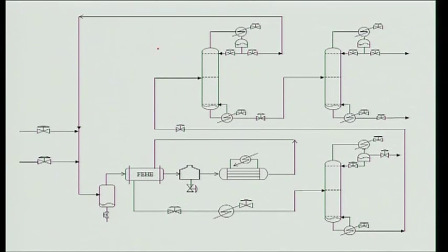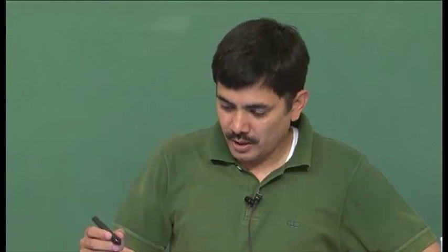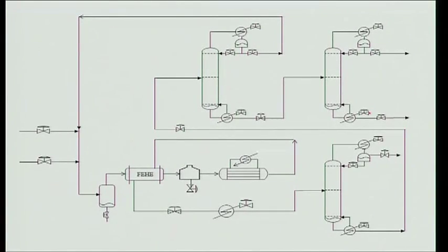Well, what we say is, V2, let us look at the maximum throughput constraints. All constraints that are active at maximum throughput need to be tightly controlled. If that is what I want to do, I will put in a loop that does this, and I will say this set point, because this control is going to be very tight, can be set at V2 max without any back off or negligible back off. This will be V1 max.